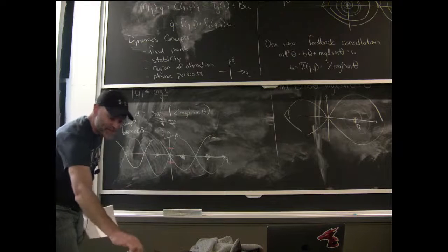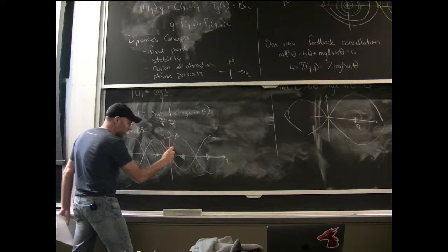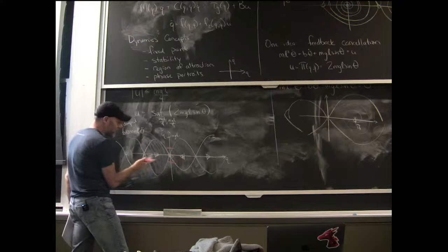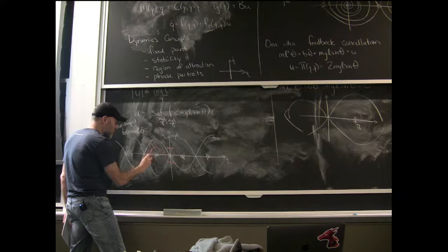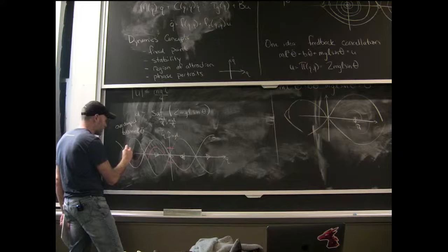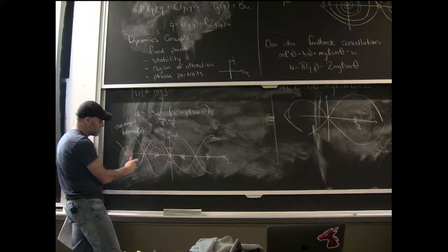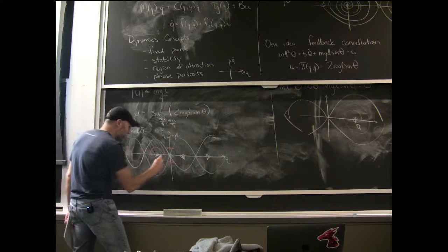The total effect of that torque limit is that when I'm inside the torque limit, it's all good. I get this dynamics. When I'm outside, though, I get truncated. This dynamics isn't perfectly canceled, and so I end up with this kind of weird thing that has some of the dynamics of the original pendulum, because it wasn't fully canceled, and some of the dynamics of my controller, in the case where I'm not saturated. And I get a bunch of fixed points.